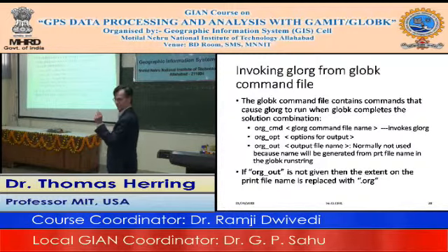Normally, we do not give this command because the output org file name will be based on your print file name: the .prt will be removed, and .org will be put in its place. As I said here, that's what we recommend, because then you ensure that the org file and the print file go together and that you don't accidentally overwrite an org file. If this is a hardwired name in here, every time you run it, it'll overwrite that file or append to that file, depending on what options you have out there.